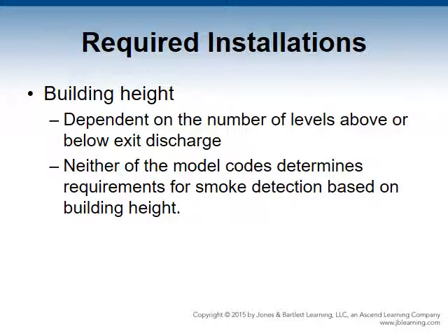Building height. The requirement does not necessarily hinge on how many feet the building is above ground or grade level. It depends on the number of levels above or below an exit discharge. Neither of the model codes determine requirements for smoke detection based on building heights.